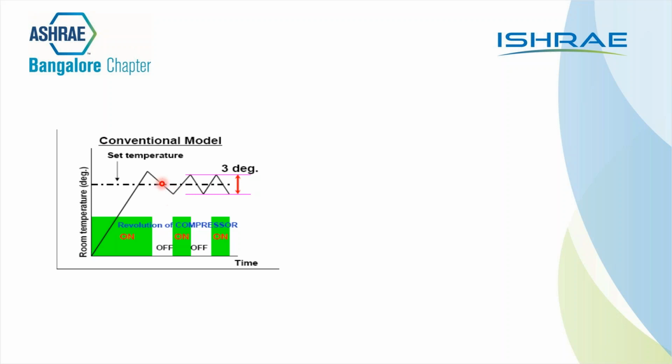Okay, thank you. So it is running at either 2800 RPM or at 0 RPM. In this condition, it is running at 0 RPM. Now, once this heat is removed, because the heat is constant in a room, the temperature tends to increase, till such time that there is something called a delta T, which is generally about 3 degrees. It also depends on thermostat to thermostat based on the setting you have.